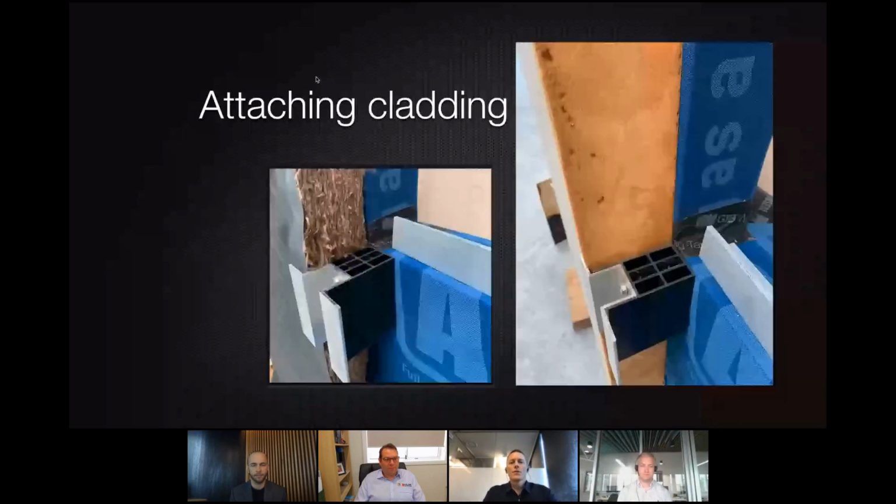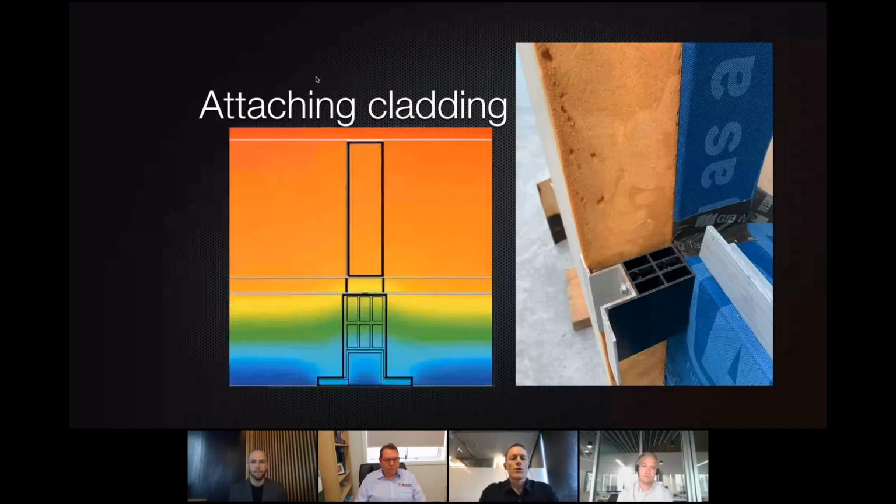And there are some options in the market, both in Australia and New Zealand for this. So this is the Technoform isolator clip. It's an intermittent connection, but it's shown here as a black polyamide with an aluminium top hat. So this doesn't have aluminium all the way through from front to back. A rail is attached outside the insulation line. The insulation compressive strength is not important, unlike the following one that I'm going to show you. Lightweight, fluffy insulation, as is shown here with the earthwall product on the left, is possible. Thermal performance is pretty good, with low thermal conductivity.